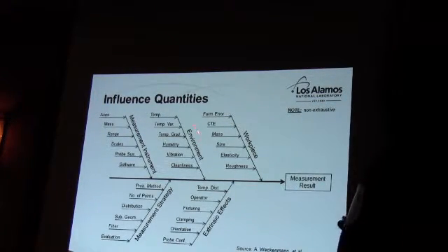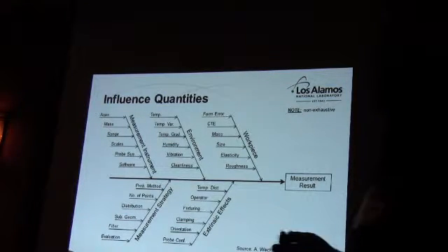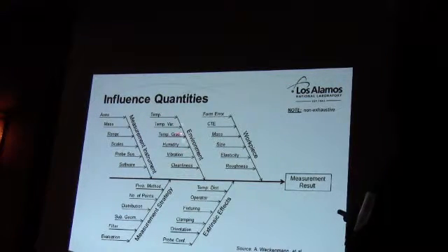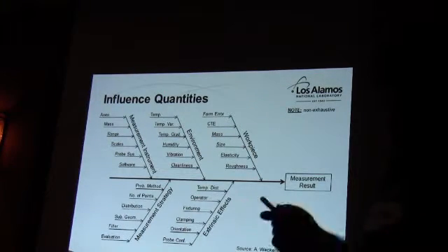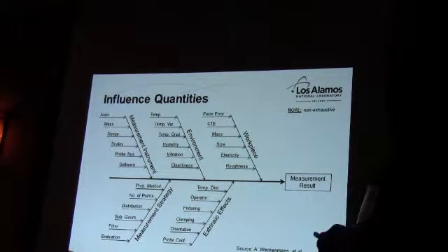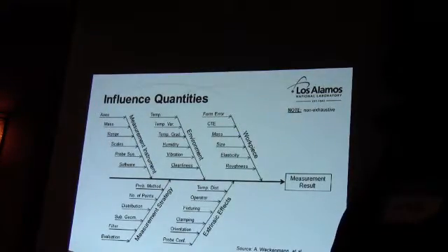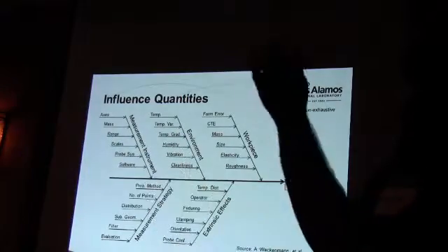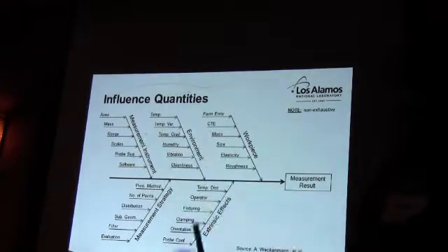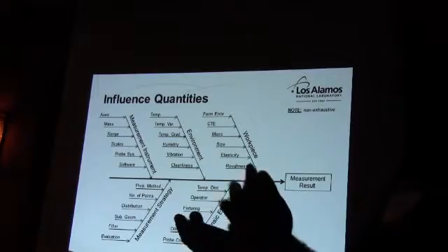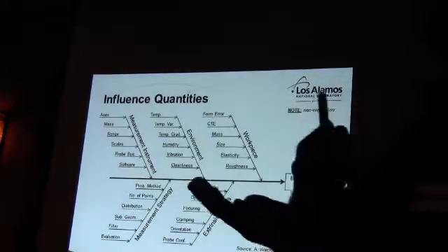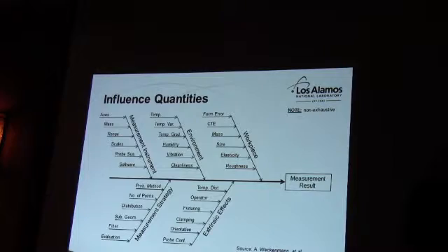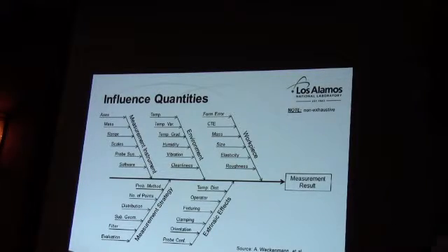The best way to eliminate this is to try your best to control it. You're not in temperature control, but you do your best to control your temperature, because that's probably the biggest issue: thermal errors. One thing to do, as I mentioned earlier, is have a test piece, a test part. You measure X amount of parts, put your test part in, check it, measure it again, and then you can look at a bias. And within that bias, you're hoping that the errors from the thermal effects are manifested in that data. That's your best way of quantifying that without having to go in and actually thermally correct everything. And that gets tricky real fast. That's not fun.